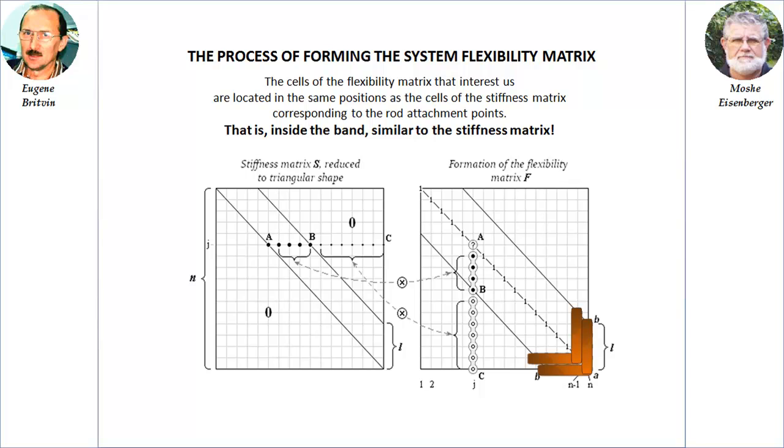For each value alpha, we build a buckling mode. Based on the shape, we determine about which principal axis of the section the bending occurs according to the given mode. Continue searching for the eigenvalues until we find the smallest eigenvalue for each principal axis of the section. Using the formula mu equals pi over alpha L, we determine the coefficient of the buckling length of the rod relative to both principal axes of the section.